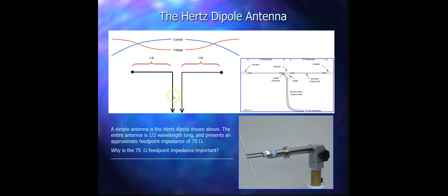And now let's talk about these conductors. If the conductor's thickness is increased with respect to the length of the antenna, then the radiation resistance of the antenna will decrease. And a typical length to diameter ratio for the Hertz dipole antenna is around 10,000 for a wire antenna, and the radiation resistance will be about 65 ohm.